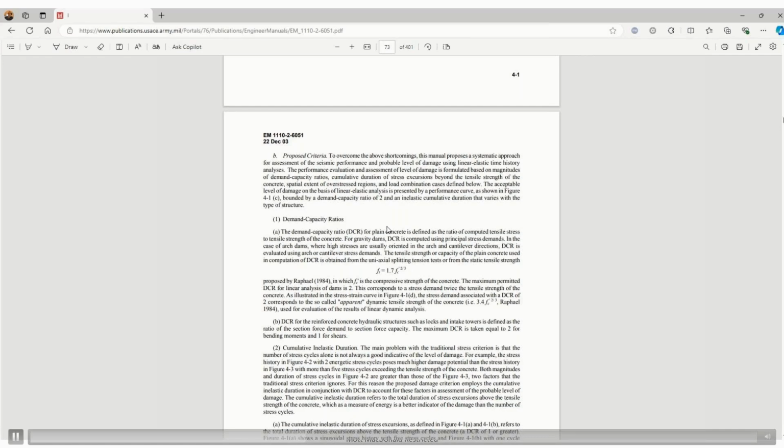For reinforced concrete structures also, there are provisions in various codes that, with the reinforcement, the RCC section tensile stresses should not exceed certain limits. For flexural tension it is say 0.7 square root of FCK, where FCK is the 28-day cube strength, and for direct tension it is about FCK by 7, I think.